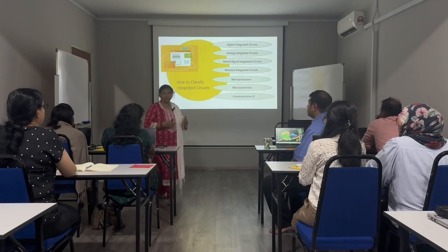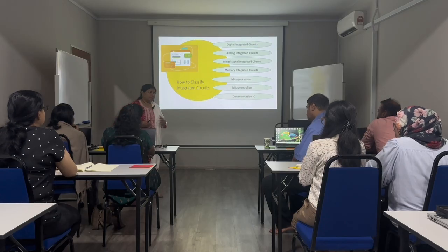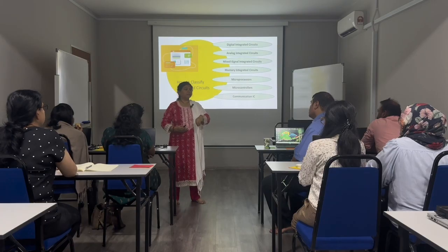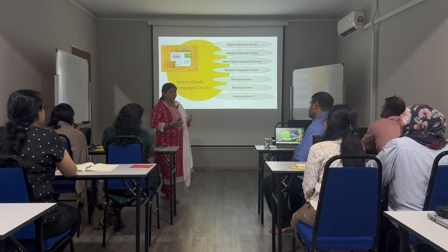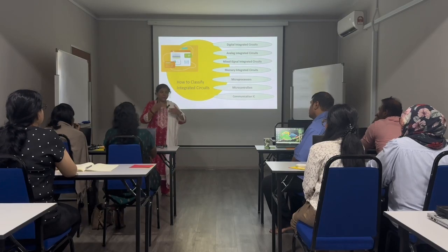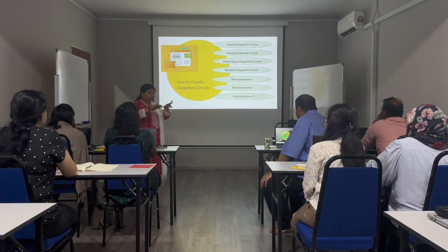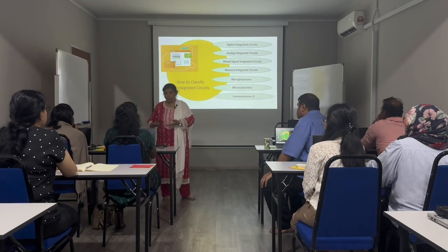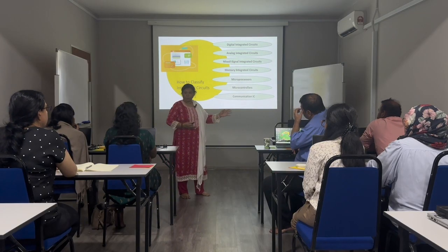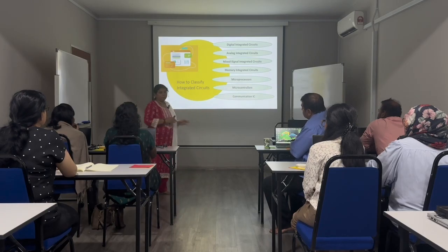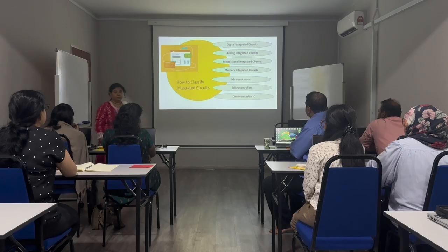The design turnaround time is also less for FPGA. When you take ASIC, the design turnaround time will be very large. The product for ASIC is application specific, so it can perform only a few applications, whereas an FPGA is multitasking and multi-programmable; multiple applications can be run on a system. The process is very simple in FPGA. You write the code, then convert that code into a bit stream because it is a machine, and a machine will understand only ones and zeros. So we convert into binary format and, through a JTAG pin, dump the application. So reprogrammability is multiple times in FPGAs. Those are the points for ASIC and FPGA.